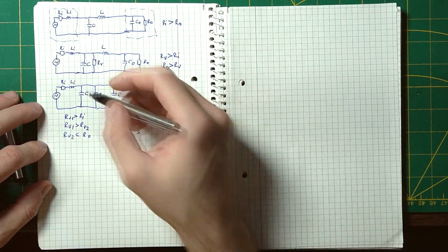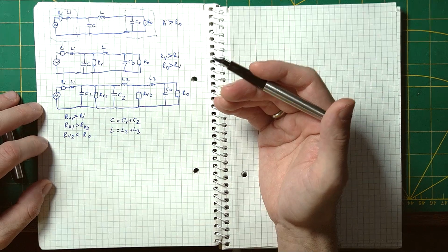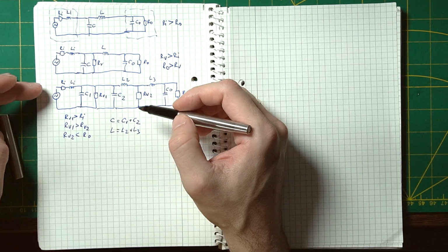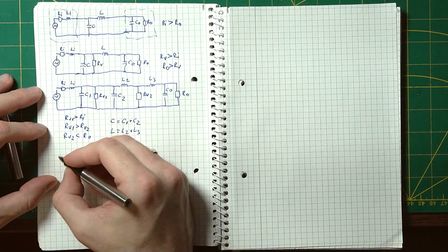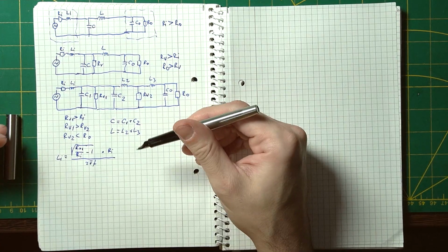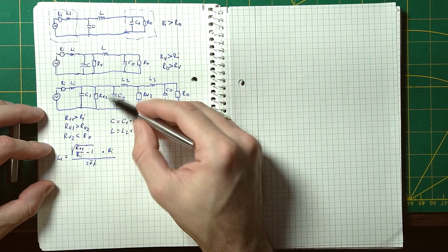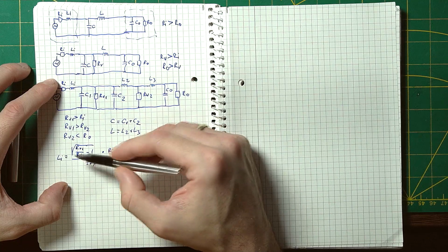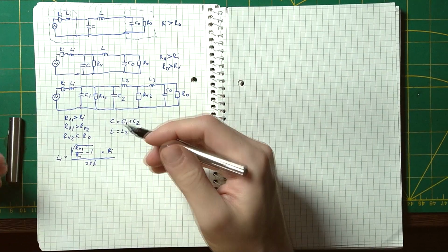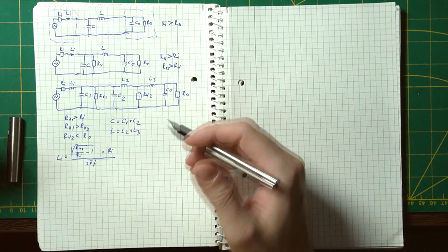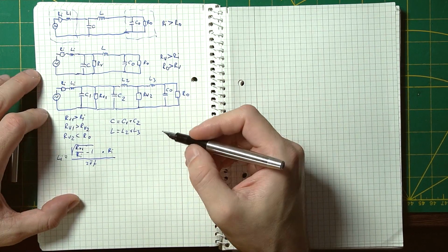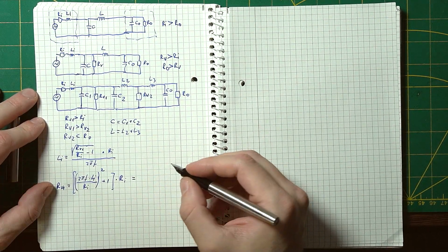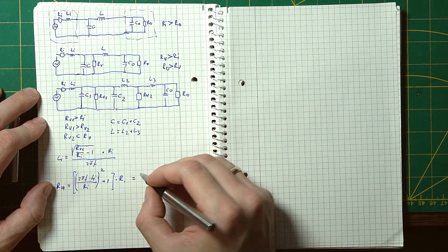First off, if we analyze our first circuit, we know from the previous video that we can calculate our matching components knowing the resistance values. The formula for the inductor, for example, would look something like this. But in our case, we don't know our first virtual resistor value. We only know the input resistor, the inductor, and the frequency, of course. So we can turn the equation around a bit to calculate what our first virtual resistor value would be.